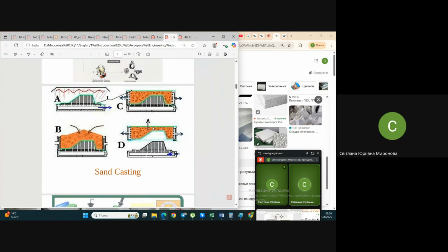Immediately after, together with pouring the material, the mold is rotated along the longitudinal axis, and due to this, centrifugal forces make material move faster inside and apply better to the surfaces of the mold. And that is why it's poured, distributed inside equally, quickly, without inner barriers, without problems with filling the mold itself, and better surface quality may be achieved also.